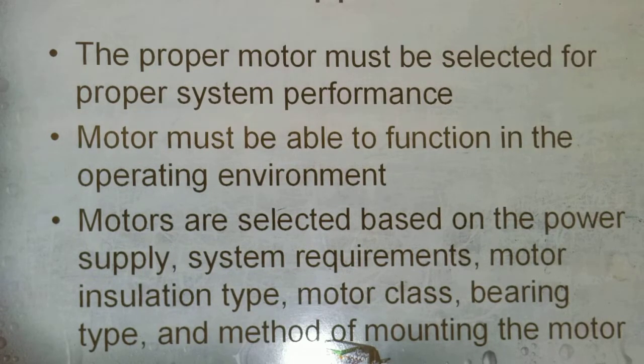Motor applications. The proper motor must be selected for proper system performance. Motor must be able to function in the operating environment. Motors are selected based on the power supply, system requirements, motor insulation type, motor class, bearing type, and method of mounting the motor.